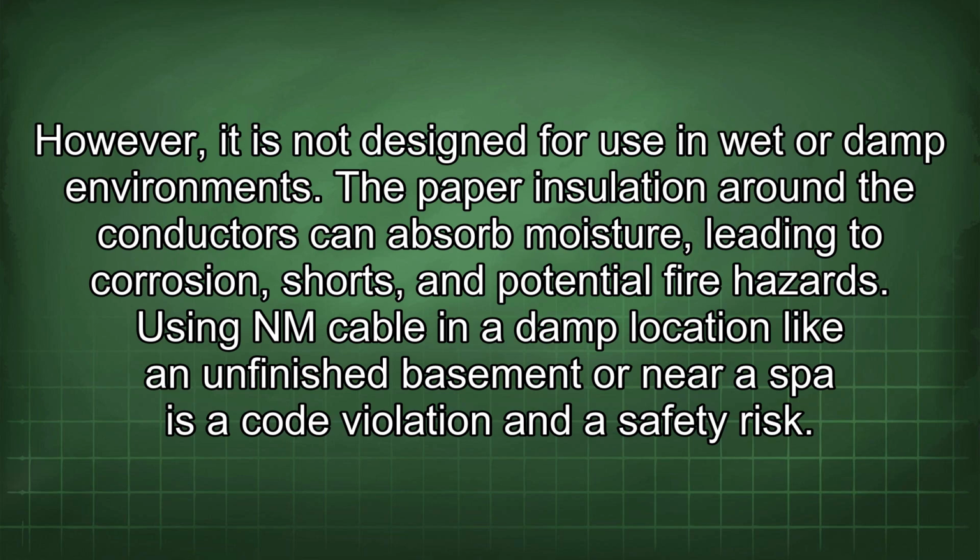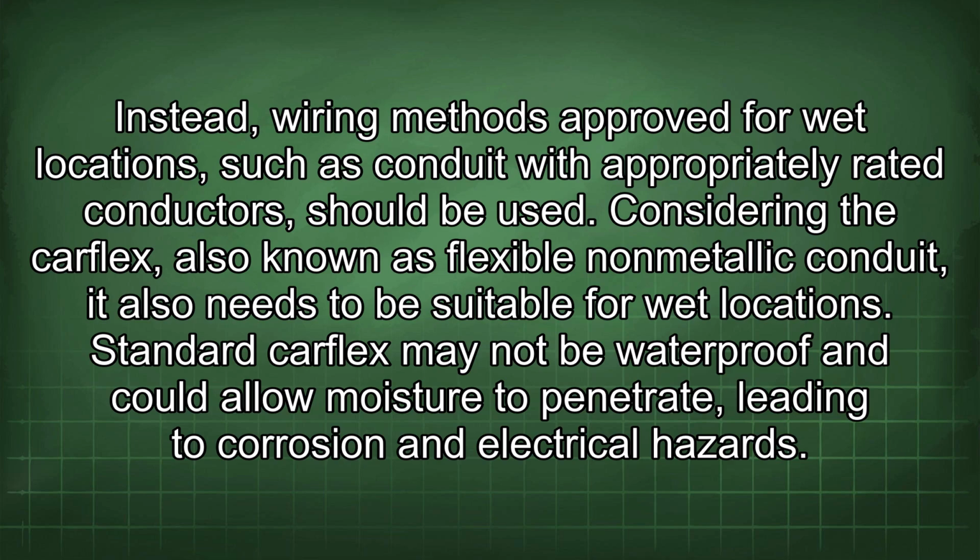Using NM cable in a damp location like an unfinished basement or near a spa is a code violation and a safety risk. Instead, wiring methods approved for wet locations, such as conduit with appropriately rated conductors, should be used.